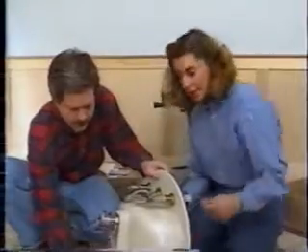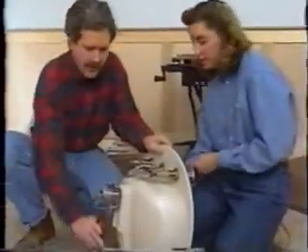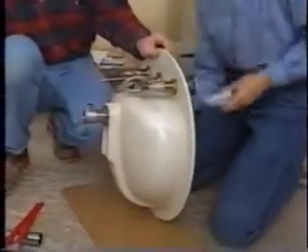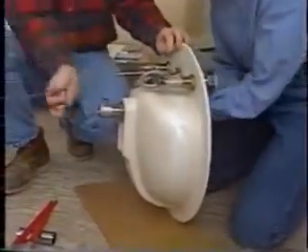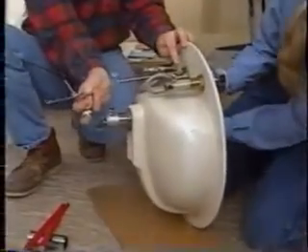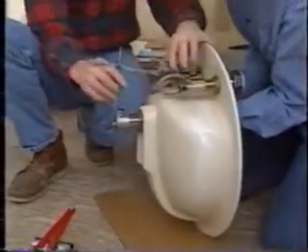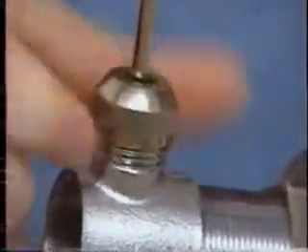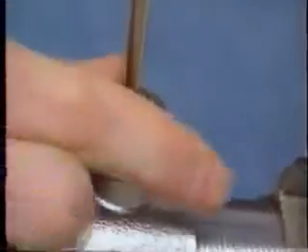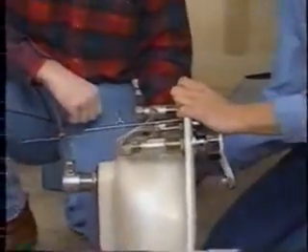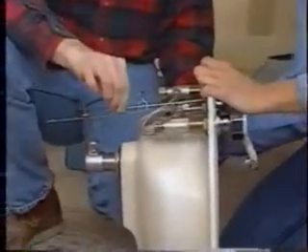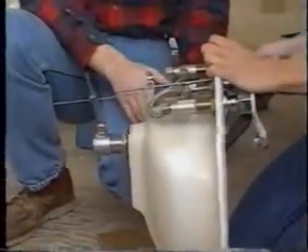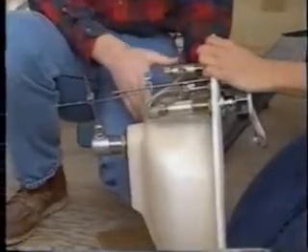The stopper lift arm slips through a hole in the top of the faucet, like that. And then the stopper itself can go down through the opening in the drain. And then we hook up the stopper linkage. If you hold that still there. And we just hand tighten this for the time being. All right, now pull the drain open so we can adjust the stopper arm. That looks good. And tighten it down. Works. Perfect.